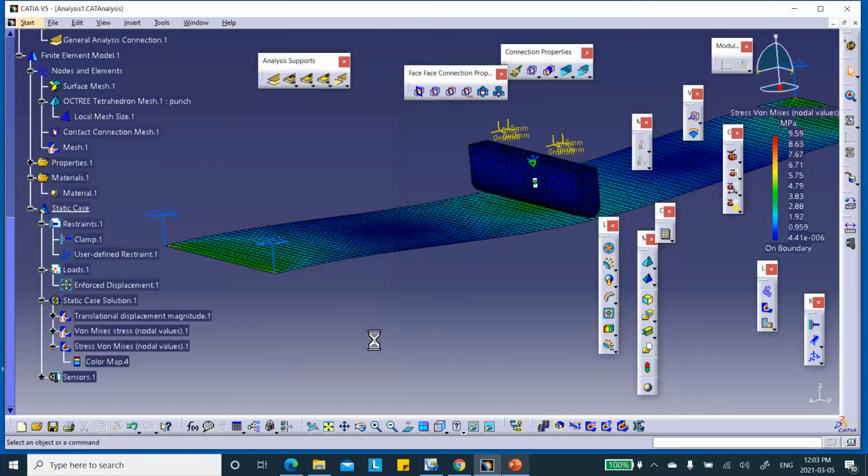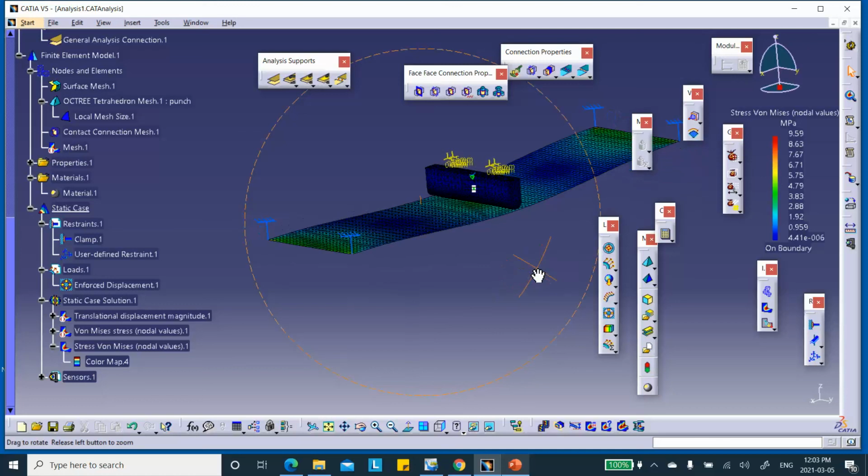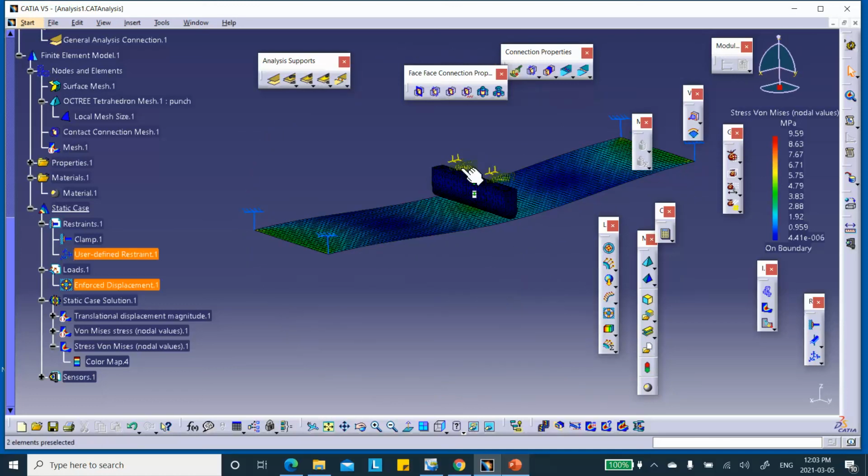And anything else that we have done before in the last 34 videos, you can use to proceed with analyzing the stresses in the fabric, etc. So these are 2 layers of fabrics. Layer 1 is the bottom one, which is oriented at 45 degrees, and layer 2 is the top one, which is oriented at 0 degree. Okay, I don't have to say 45 and minus 45 because these are plain weave fabrics. If the orientation of one of those yarns was 45, the other one is minus 45.